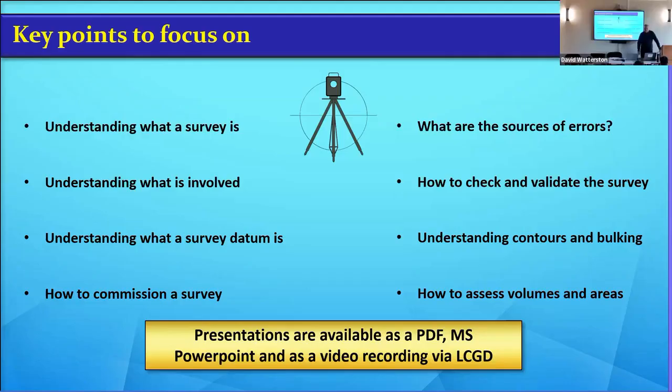If you're working for a large company, you may inherit surveys. And if you're going to do a basic design on that, you need to know, is it any good? So you need to start taking a few dimensions across it, eyeballing things in. I'll show you some pieces of equipment that you can use to assist you in that. They're low cost. Because before you do anything, you need to make sure that survey is any good for you to work with. All right? But at the end of the day, hopefully, you'll get an idea of all this.